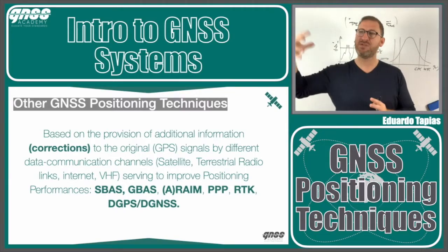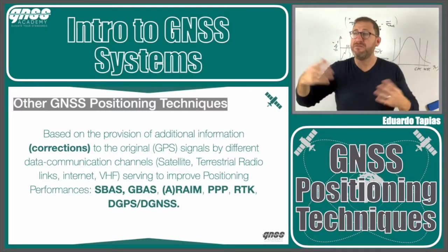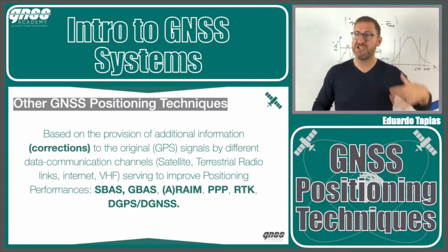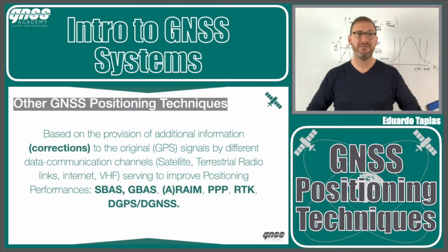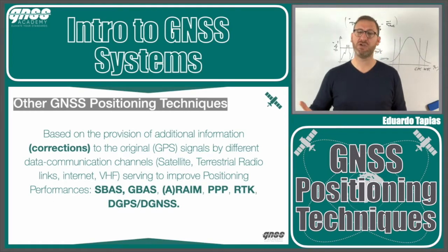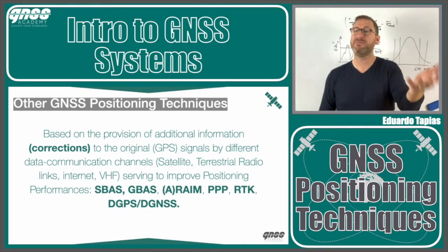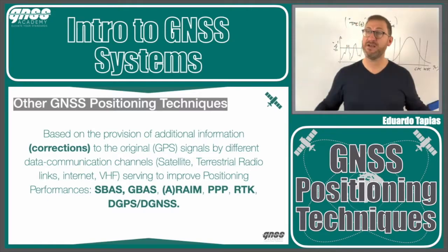I have some sources providing me with corrections and information via different channels, for example a geostationary satellite, a terrestrial link, internet, VHF, 5G, whatever channel I have. I want to improve my positioning, so I have the SBAS techniques, GBAS techniques, RIME techniques, PPP techniques, RTK techniques, differential GNSS techniques. Different kinds of techniques to estimate.